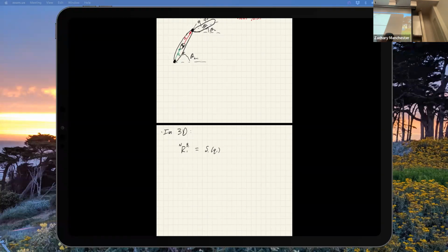So this guy is unique to each link, or each joint type on each link, and it encodes what that actual joint is doing, like which way it's rotating, et cetera. So I'd have to write this guy down. Notice this is S sub K for each link, to encode which way the joint goes, basically. Does that make sense, everybody? So you've got to write that down for each link, each joint.